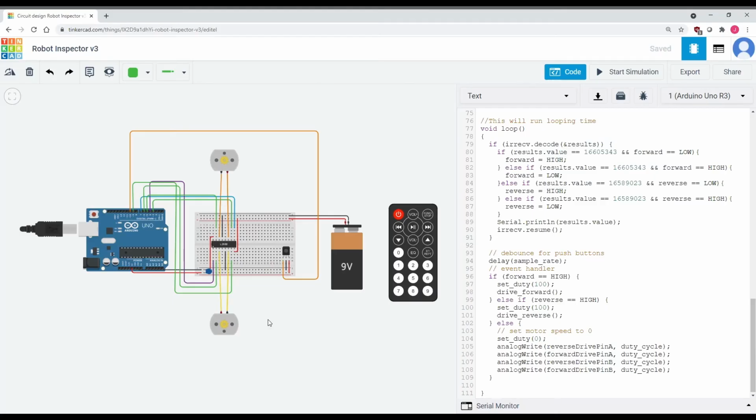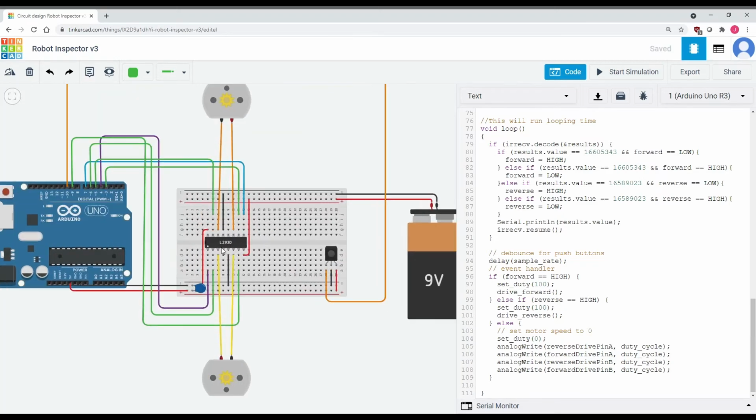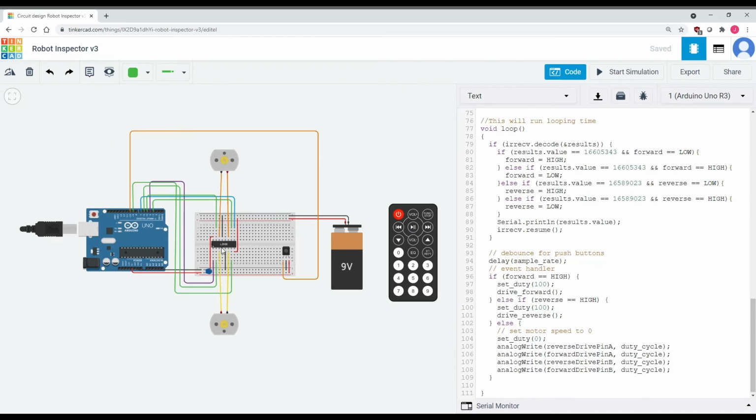The motor driver, which is the L293D motor driver H-bridge used in this circuit, is the key to operate and control the DC motor's speed and direction of rotation. In this electrical circuit, an UNO R3 is implemented with the H-bridge circuit to control the operation of two DC motors, which will control the treads.